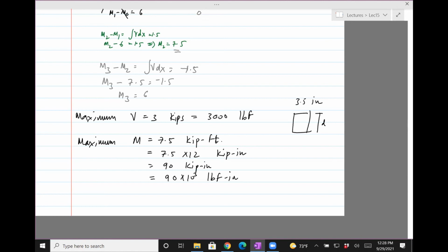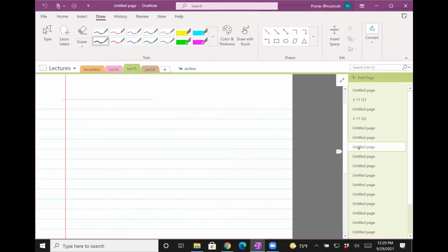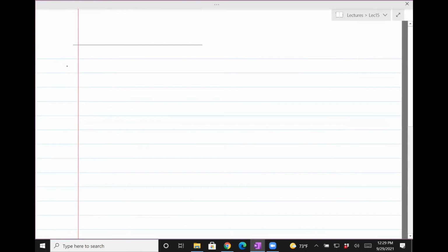Okay, so we are now ready to solve for the diameter. We need to find this diameter. So step 2 is to assume that the beam fails when the normal stress is exceeded, that is exactly midway where M is max, and use those formulas to find the D. So second step, assuming, use normal stress for design.